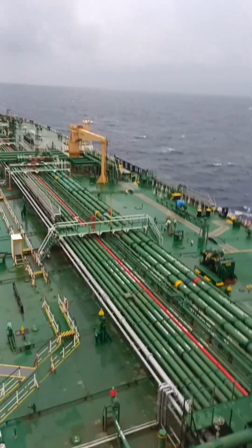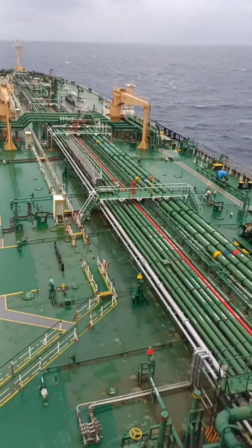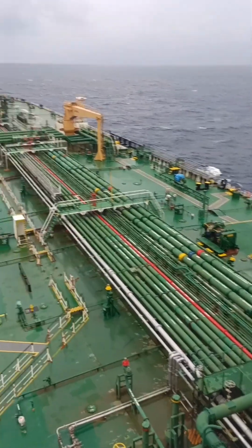Okay friends, so basically what happens on oil tankers, there are a lot of pipelines given. As seafarers, you may know there are a lot of pipelines. At the end of discharge, after completion of discharge, whatever lines are on deck, we call these the top lines, then bottom lines, separators, strainers. All these lines we need to drain properly. After completion, a separate line is given. Whatever oil we are draining after discharge, we are discharging this oil with the help of this Marpol line.